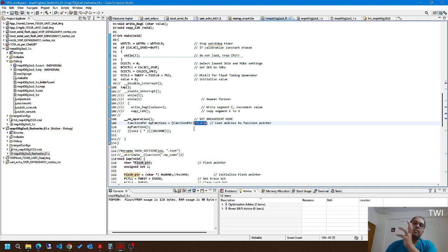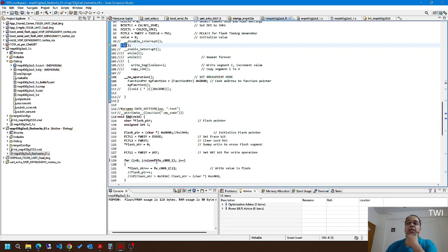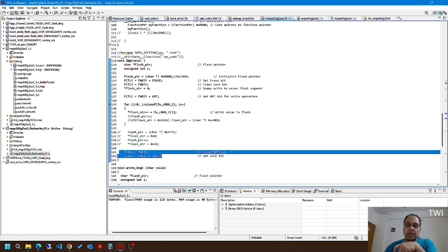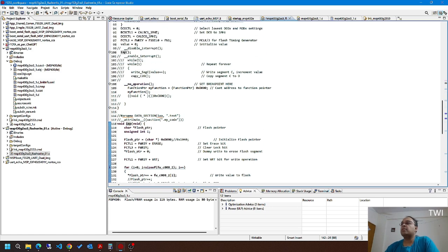So one thing you need to remember is that when you are inside IAP, it is better not to open the debugger, because your IAP will be releasing the flash memory controller only after executing the last lines. If you halt it in between, the flash memory module generates a higher voltage in order to program the flash memory, so your flash memory will be stressed in order to check the values. It's better to avoid that, because the flash has a limited number of read-write cycles for any of the devices.